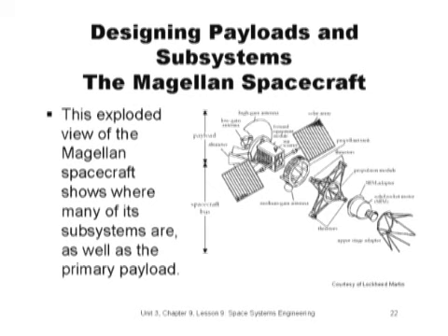The Magellan spacecraft bus has a large high-gain antenna, as well as smaller medium and low-gain antennas for communications and data handling. Many different structures like equipment modules, thrusters, tanks, and adapters are used to keep different parts of the spacecraft in place. The solar arrays provide power. A star scanner is used to determine where the spacecraft is pointed. So you can see that the spacecraft bus is similar to the school bus in that it provides for the care and feeding of the payload.